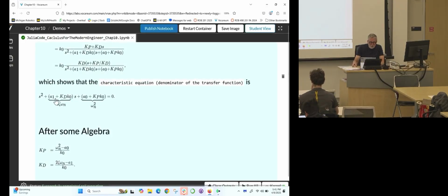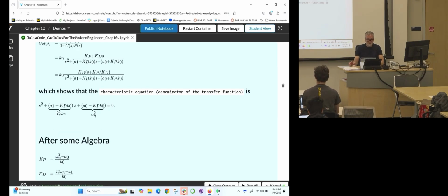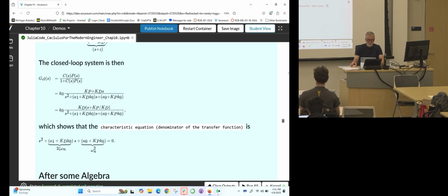There's the denominator of a standard second order system, and we perfectly did it. I know you guys did. Okay? But look, is this omega n squared up here? This is the numerator. That standard second order system had omega n squared. This coefficient repeated here. And the answer is no.